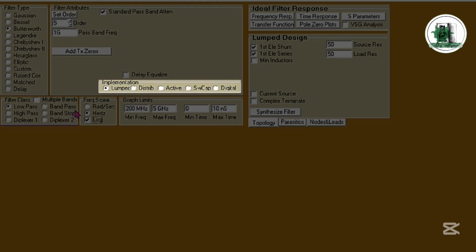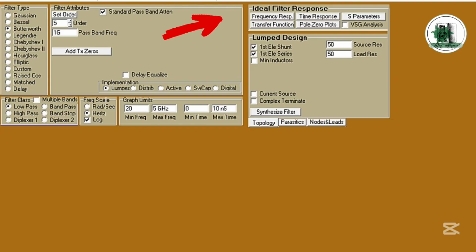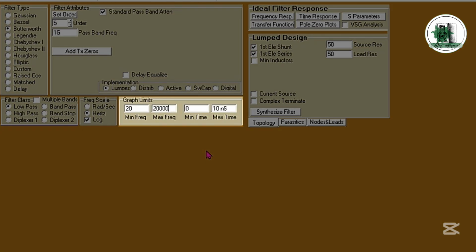In this video, we'll focus on passive filters. The first assumption we'll make is that the driver has a flat impedance, and all the explanations from this point forward are based on that assumption. If you like, you can watch this to learn how to flatten the impedance response. As you know, our hearing range is roughly between 20 Hz and 20 kHz, so make sure to enter that range into these cells to get meaningful results.